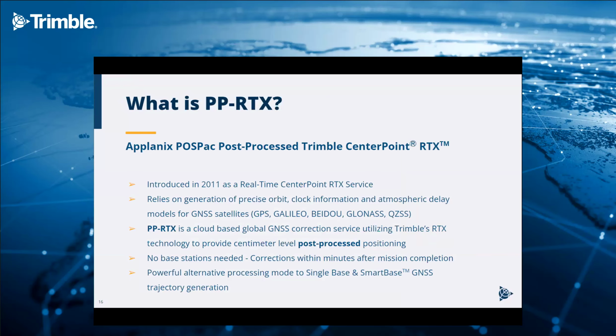Well, for our PPK processing, the interesting part is obviously the post-processing mode. So we call this Applanix PPK, post-process Trimble CenterPoint RTX, in short PPRTX. As I said, it was introduced as a real-time CenterPoint RTX service at the beginning, and that goes back to 2011. And it relies on precise orbit and clock information and atmospheric delay models for GNSS satellites.